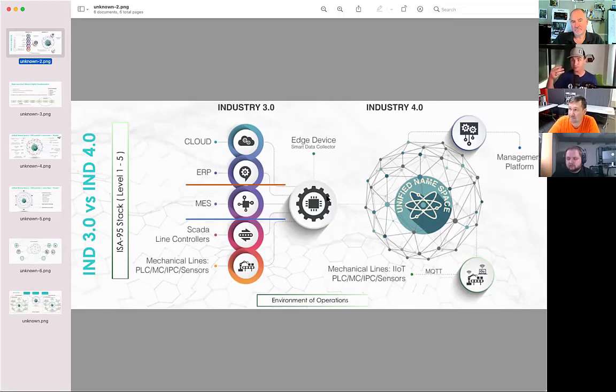So every time you add a new piece of equipment on your plant floor, you've got to go into your OPC UA server. You've got to enter in the device. Sometimes you've got to add the tags, not always, but if you don't add the tags, your clients that are connecting to your OPC server have to know what those tags are, right? There's no self-discovery going on. Self-discovery comes from edge-driven. If it's server-driven, you have to know what to put into the server. So it's not scalable.